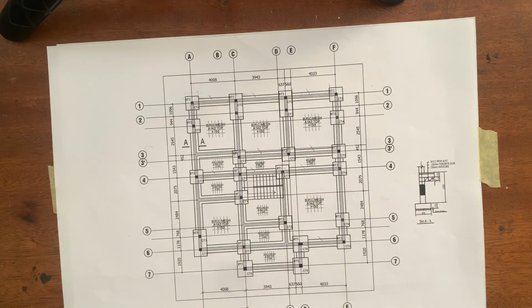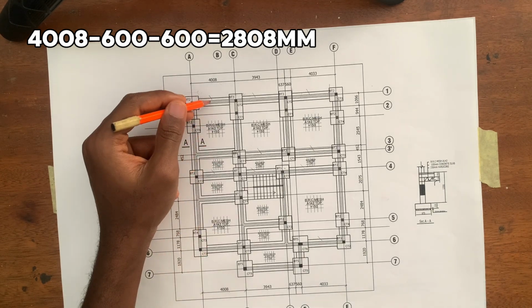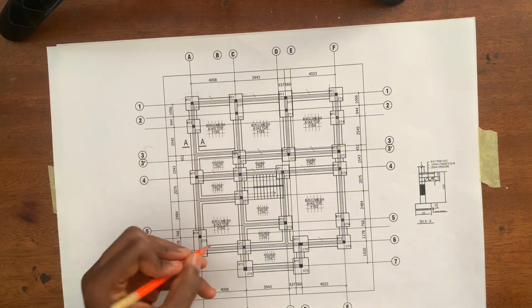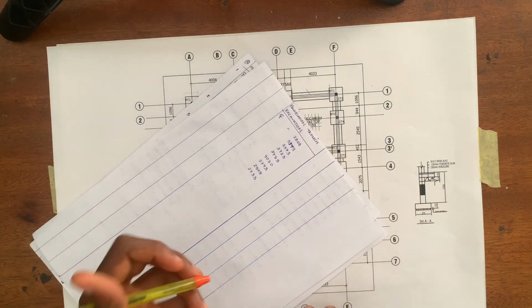What is the length of base type 4? The length of base type 4 is 1,200 and that of base type 1 is 1,200. So half of it will be 600 each. So we can now minus this half and this half to get this length. So 4,008 minus 600 for this half and minus 600 for this half is going to give me 2,808, the same thing that we've gotten here. So we will now record it: 2,808.